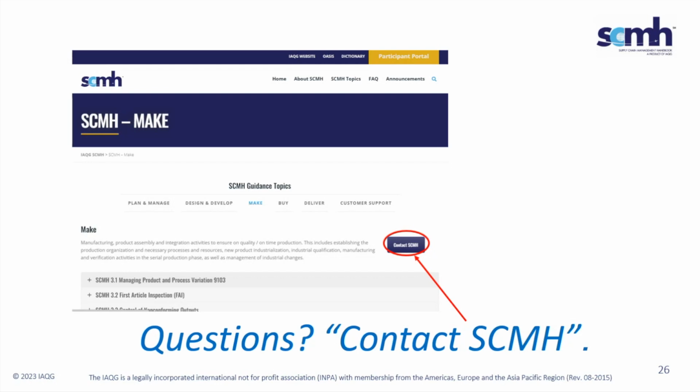All right, awesome. That answers that question. Here's a good question. I will read it almost directly. If your customer only provides you with a model-based definition, does a supplier have the responsibility to create and balloon information needed for the first article? Yes, the supplier would need to extract the information from the model that's needed for product realization to create the part.